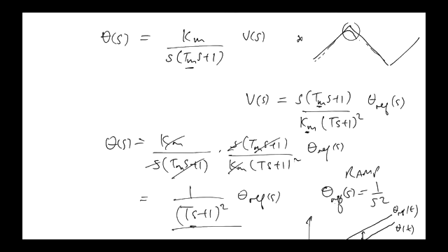You should have observed that for the 2 different motors, you need to choose different parameters to make the simulated response match the observed data, because there's slight differences between the motors. In other words, you cannot know the model parameters exactly. Right? You'll get some numbers, all right, but the real motor will behave slightly differently.